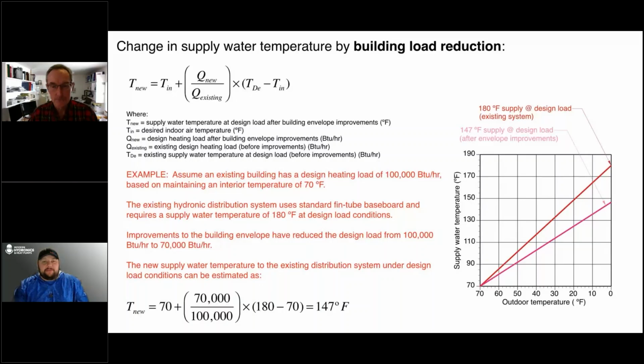We do have one other question here real quick. Your thoughts on adding small fans to existing large cast iron radiators to increase heat output at lower water temps? Yeah, it would. The limiting factor on a radiator is basically convection, and anytime you improve the airflow rate over a surface, you're going to improve the convective heat transfer. So yes, in theory, you would get more output.